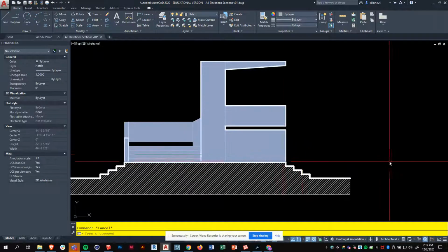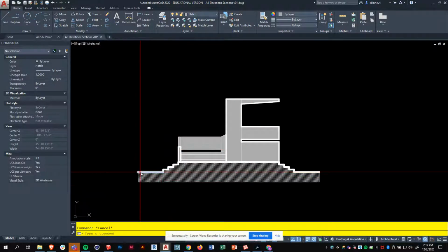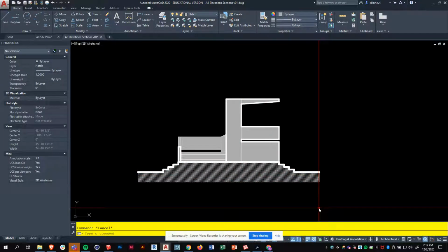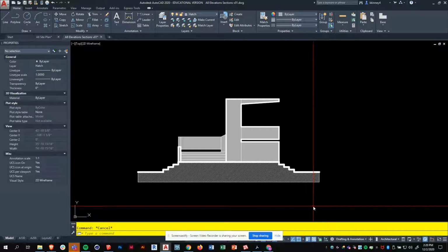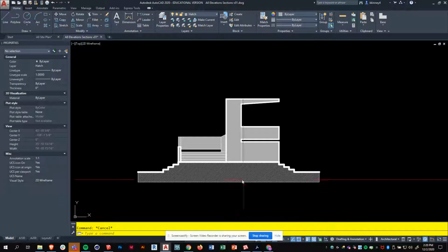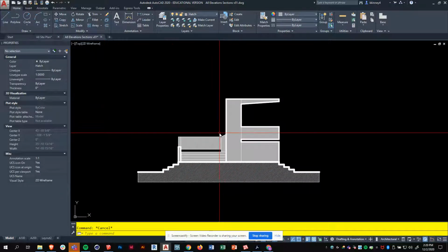Okay, now that is a beautiful section drawing. Of course, I'm going to have to test print this and make sure it really reads nice. What should read the darkest is, of course, your dark cut line weight, and then kind of this hatch. But I don't want that hatch to compete with the line weights. The hatch is just supposed to add clarity, so try to be as clear as you can so that when I look at this, it's clear. But this looks really nice.